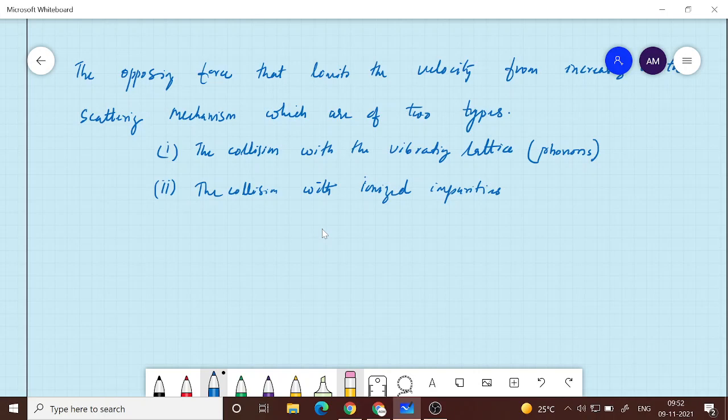The ionized impurities have a Coulombic potential associated with them. For example, once a donor atom gives away its electron, it acquires a net positive charge, and this potential becomes visible to the electron when it moves near, and it gets scattered off. They get attracted by that potential. Or if it is an acceptor impurity atom which has accepted a fourth electron, it will have a net negative charge, and that will try to repel the electron or attract a hole.